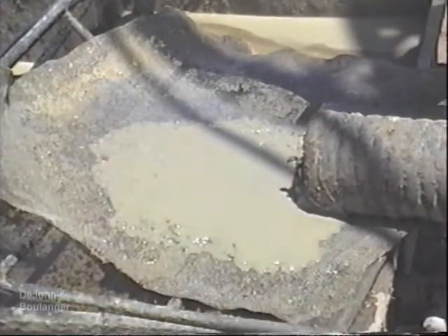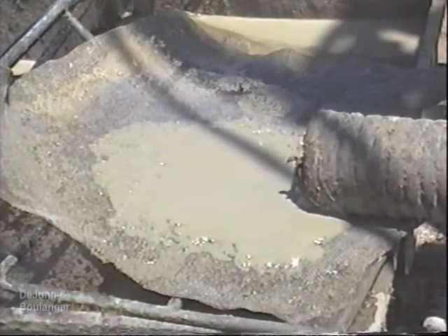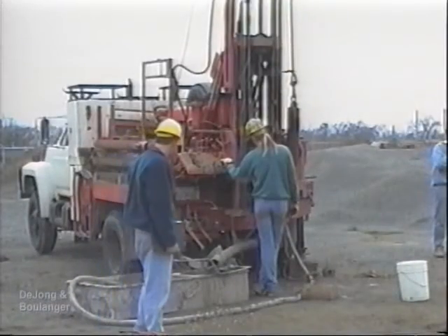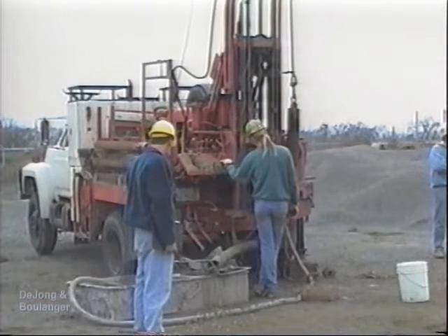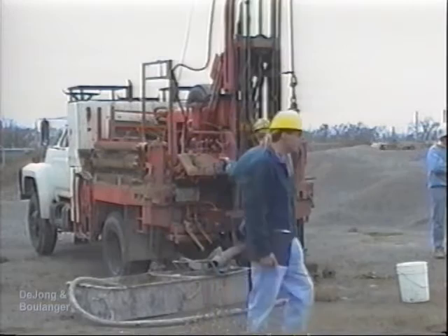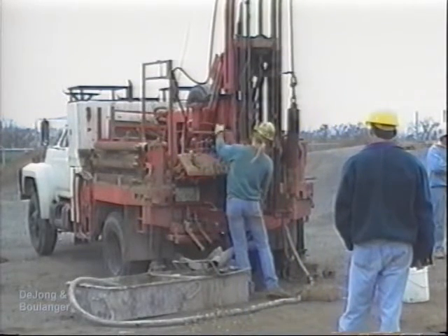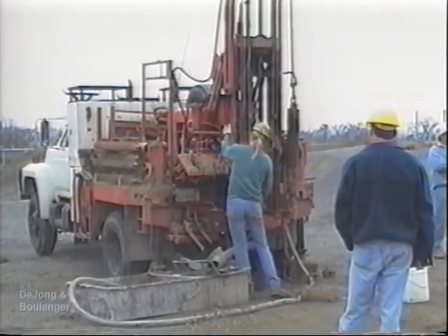At the top of the hole, the mud pours out through a catch screen into a mud tank or settling basin. The mud tank has several different compartments that allow the cuttings to settle out. At the other end of the mud tank, the pump again draws the mud, which is now free of cuttings, for reuse. The drilling mud also serves as a coolant for the drill bit, preventing excess wear.